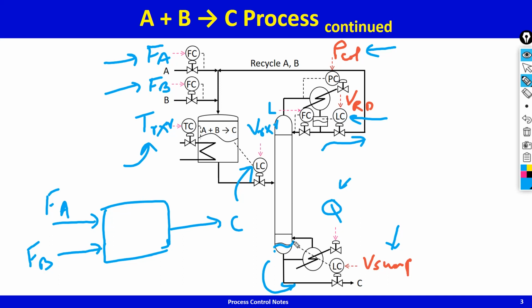So if I set this at 100 kilomoles an hour, and let's say I set this at 110 kilomoles an hour, even though I know they should be equal, I may set them to be equal, but then 10% flow error is very routine, so they may still be off by 10 kilomoles an hour, so that's fine. Then at steady state, do you see that A, because there is no quality control here,